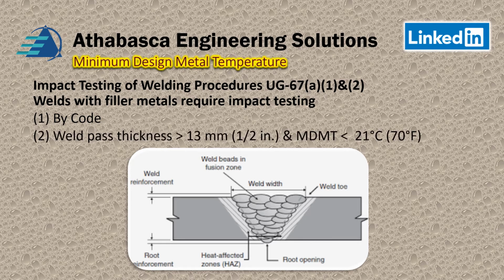And when the weld pass thickness of any individual pass exceeds 13 millimeters, which, if you want to be really exact, is half an inch. And the MDMT must be colder than 70 Fahrenheit or 21 degrees centigrade.